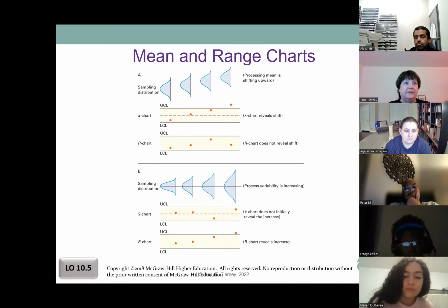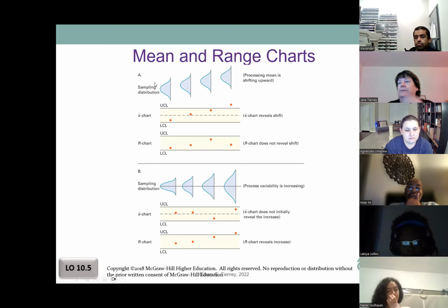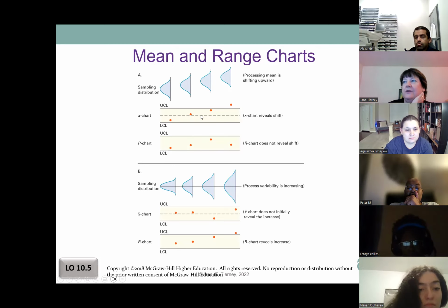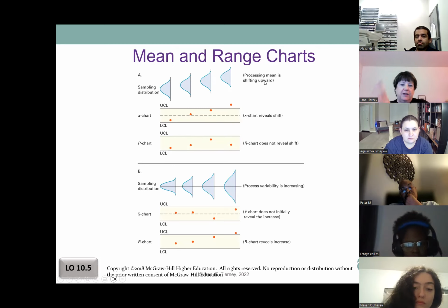So what this tells us, if you have this kind of combination, is that we're keeping our curve the same size, basically, and the same amount of variation. Sorry about that, I'm drawing on the wrong one. So we're in the range right here. So this looks good, but this says, okay, we've got a problem because we've got this trend and it's getting worse. So what it tells us is our mean, our average, is moving. So the process is shifting upwards.